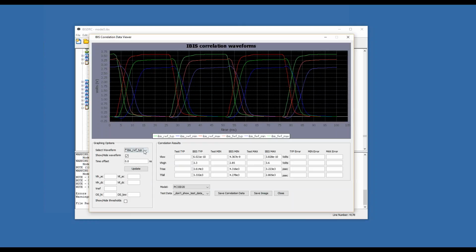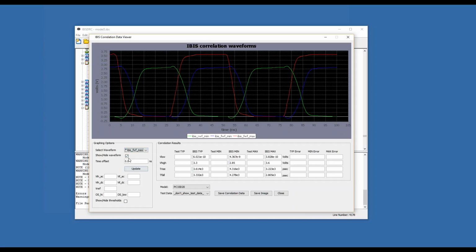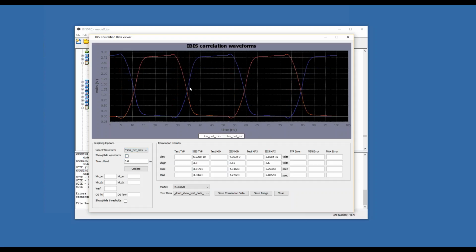Right. So let me turn off all the corners except for the min corner, which is your slow corner. So you can see here's your slow corner transitioning up to 2.85 volts, which is the VCC in the min corner. It's going to be whatever, -5%, 10%, whatever, fine. Switch to 0. So this one looks okay.